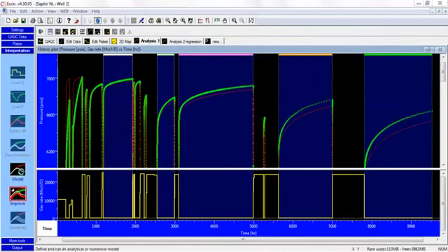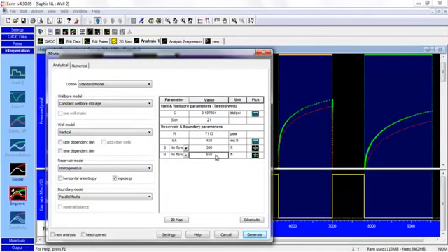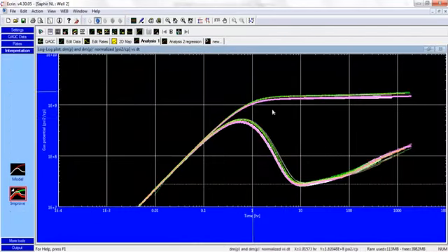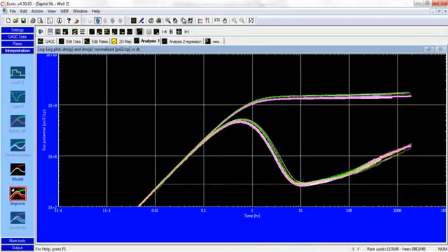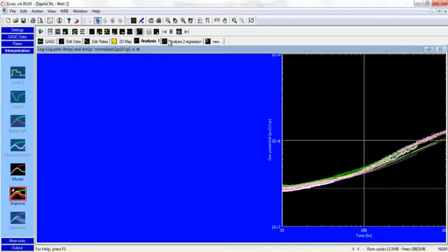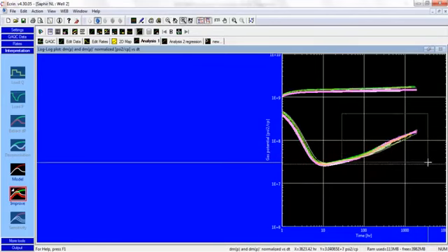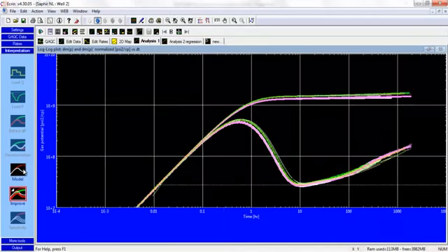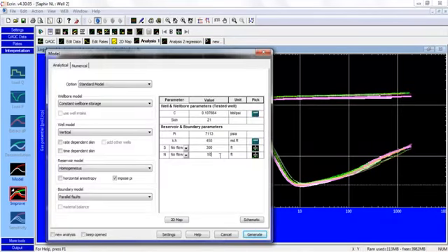Another thing we could do is maybe increase the distance to the boundary. Maybe let's say 700 feet. Again, it's better. It's not perfect, but it's a bit better. But if you look at the conventional derivative, you can see again that our model doesn't match the data anymore. As we increase the distance to the boundary, our simulation is shifted towards later time, or towards the right, and we don't match the data anymore. So that again is not the solution. So we go back to 550.